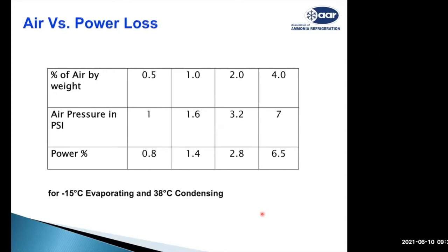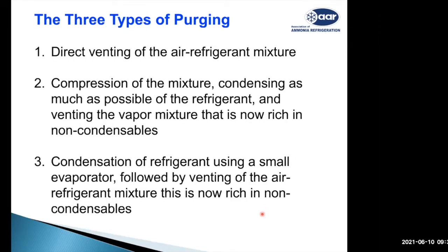And as I told you, when the pressure increases, there is also a possibility of ammonia breaking into nitrogen and hydrogen, which makes both of these gases non-condensable gases in our refrigeration plant, and definitely affects performance, in addition to the air. And once we have air in the plant, our discharge pressures and temperatures are higher, and the possibility of oil breakage is there, which also leads to the addition of these non-condensable gases.